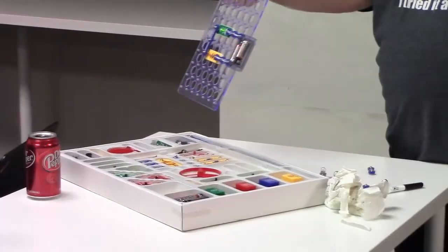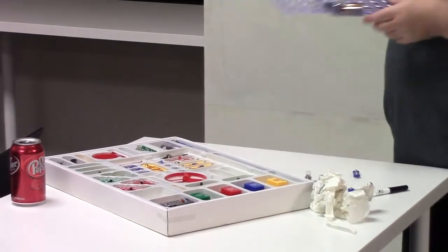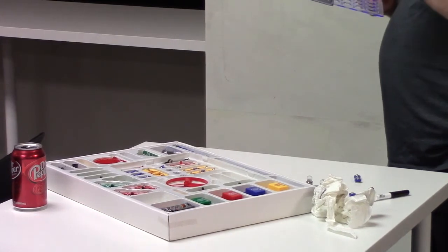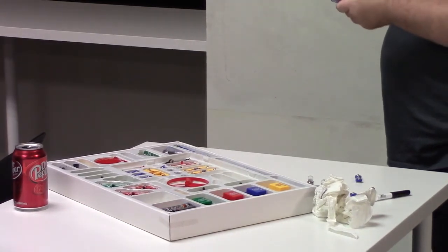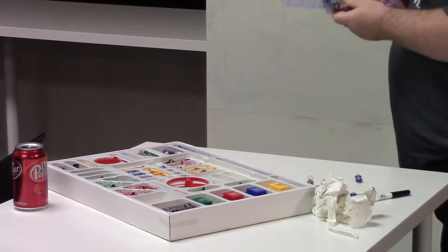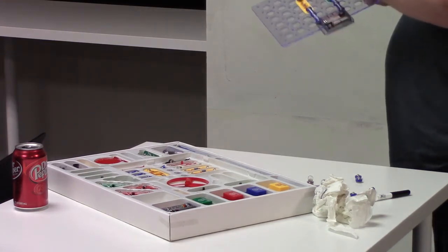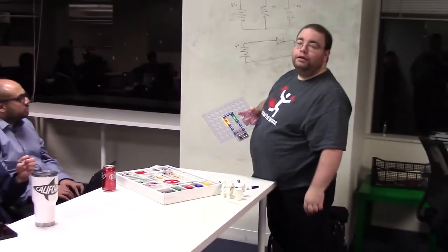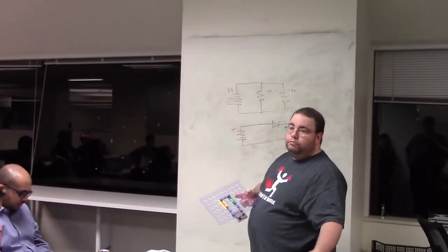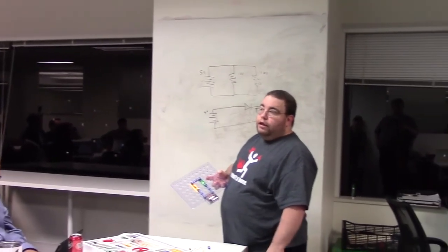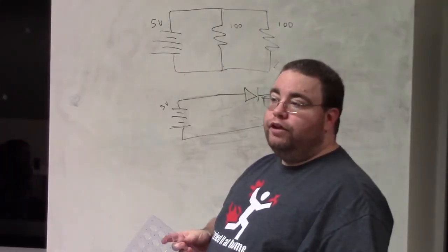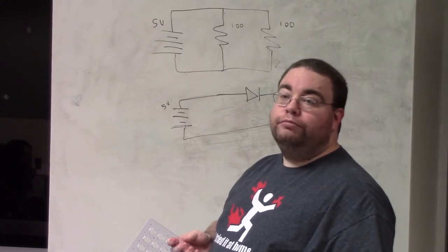Does it matter if the resistor is before or after? It does not. I mean, kind of, no, it shouldn't matter at all, actually. It's the same. It's all a circuit. Because either way, you're still going to have 4.3 volts going through the resistor, because the LED will always drop 0.7. How do you do it when you're building stuff, do you put that resistor on the other side or on the first? At this point, what I'm usually doing is laying out boards, and the best answer I can give you is how it best fits on the board.